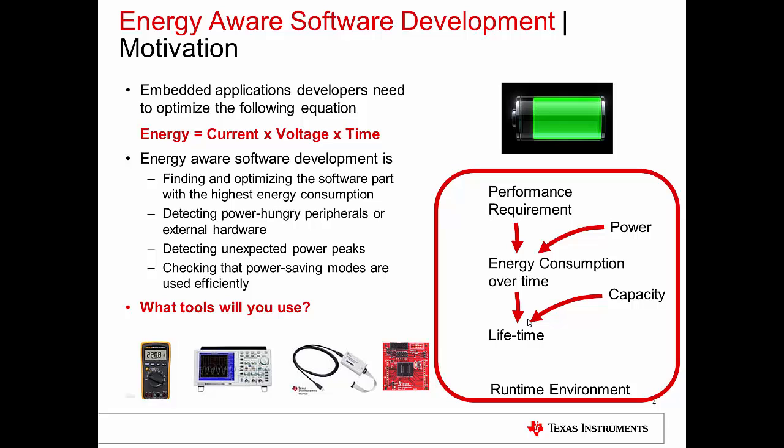So what tools would I need as an embedded engineer to accomplish this goal of analyzing my energy consumption? You as a software developer will most likely resort to these few pieces of equipment that you will see here on the bottom left corner. You probably need some kind of multimeter. If you want to do current profiling, generally you will need a shunt resistor on there, hooking it up to the scope and looking at your power consumption, and the necessary FET programmer and target boards.